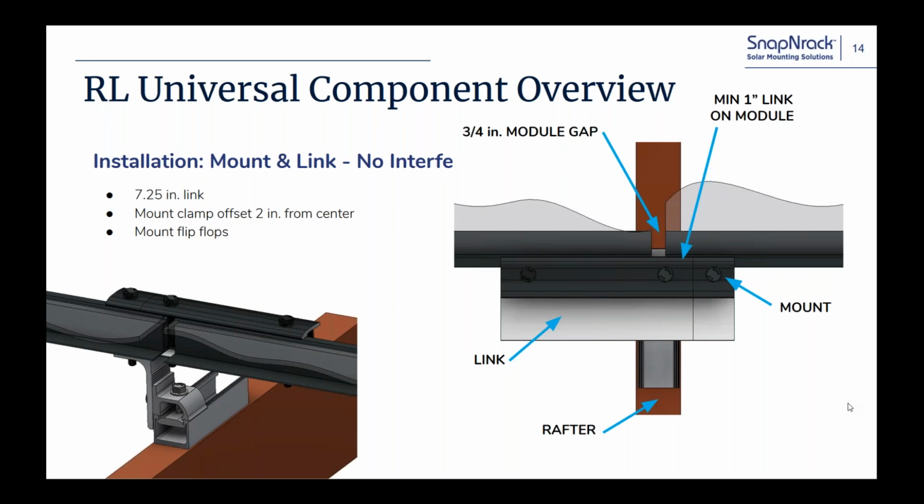So he's found all the rafters. The guy behind him has worked on all the pilot holes. And then as the guy finishes the layout, he'll come behind the guy drilling the pilot holes and break open the composition. And then once the guy that was finding the rafters has done all that, he'll come behind and start applying sealant and sliding the flashings in place. And I recommend applying the flashings as you break open the composition all at once.